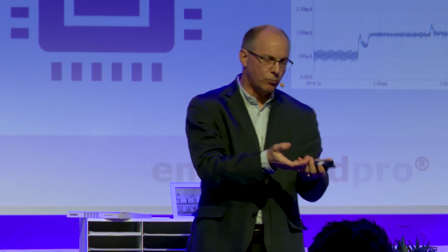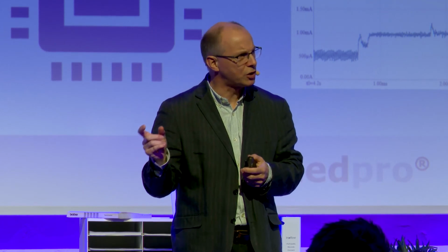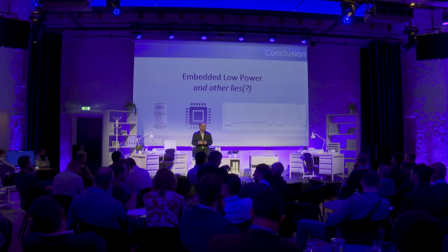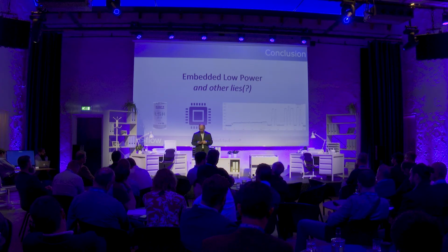You're going to need RAM, which you probably get as a RAM cell in your FPGA. You might need some flash, so you're going to have an external flash memory. Don't underestimate how cheap these external flash memories are. Great. But don't underestimate how much current those external quad SPI memories actually take when they're up and running. So FPGA, yeah, you're in control. Now you need five software engineers doing the FPGA design in Verilog to make the system that you're trying to do.